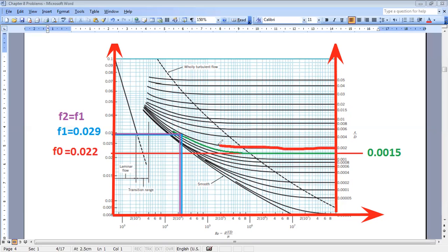and then here it is going upward. So if I give you, for example, Reynolds equal to 10 to the power 6, this is Reynolds 10 to the power 6. I go up, okay? When I reach the intersection point, it will give me the corresponding value of f. So now I will take a new line from the intersection point towards my axis. I can read the corresponding value of f, okay? And I can give you, for example, f and Reynolds, you get epsilon over d. So you have several possibilities. Depending on your input, you decide on the output, okay?